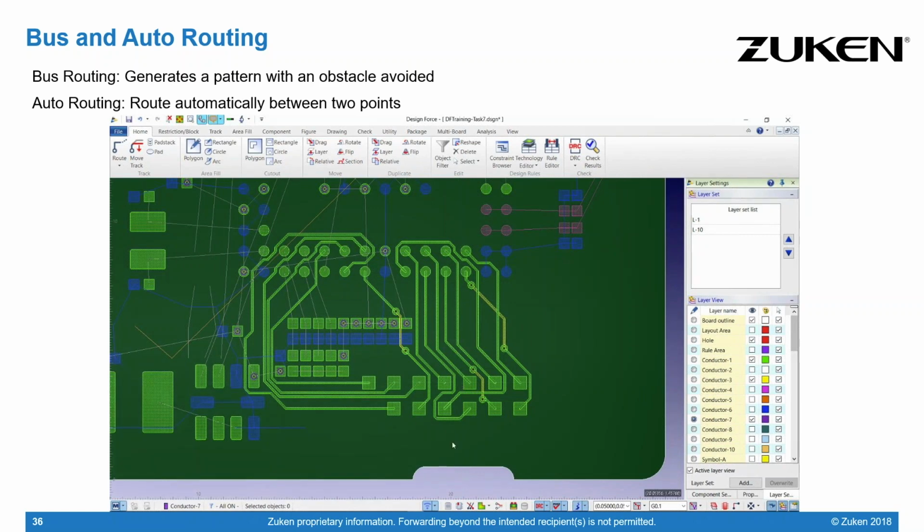So why are these two steps, bus routing and auto routing, essential for DDR5 layout? It is like a routing channel, where the layout designers can visualize the paths between the critical components. Often bus planning is tied in with the component placement, and several iterations of component placement planning are required before starting layout. So you can think of bus planning like a sketch stage, where the general outlines of pictures are drawn.